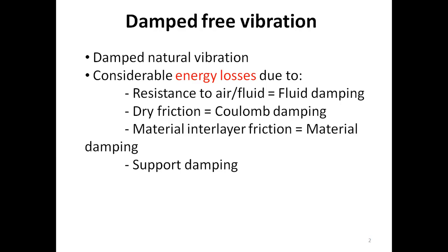For example, we have air damping, which is also known as fluid damping or viscous damping. And that damping is present in the system because of the air or the fluid around the moving parts in the vibratory system. As there is air or fluid around the moving part, as it moves, it displaces the molecules of the air and the fluid.